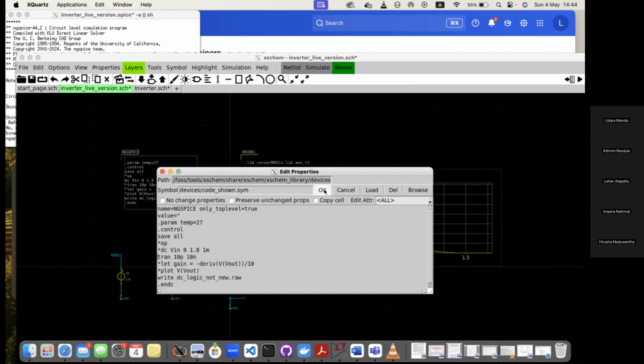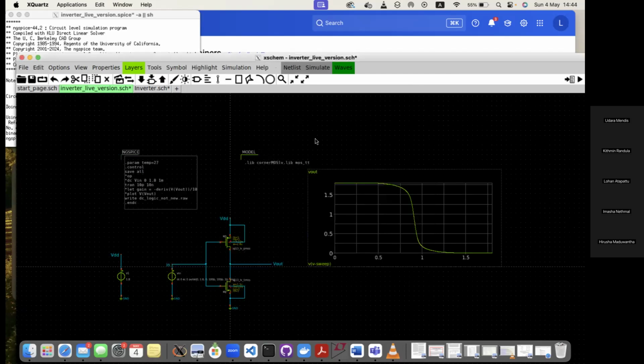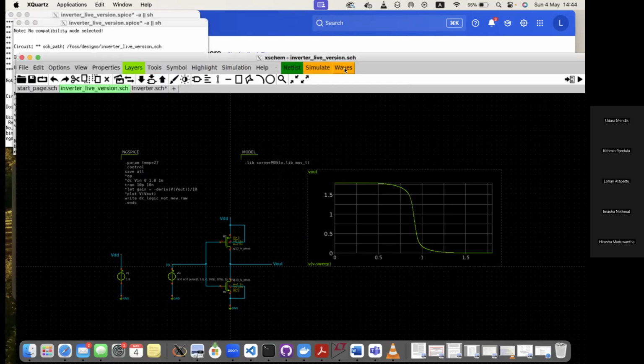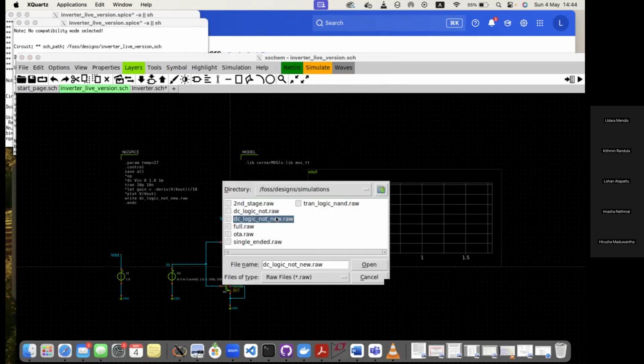A simple transient simulation. As you can see, some transient simulations will take hours, according to the step size and the time you need to check. If I use a 10 picosecond step over 1 hour, it will take a very long time to do the simulation. So I will be using a short transient.